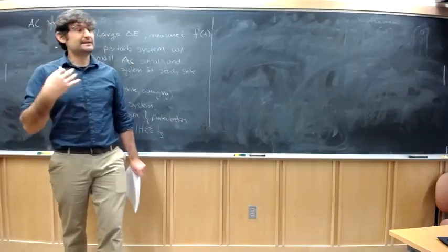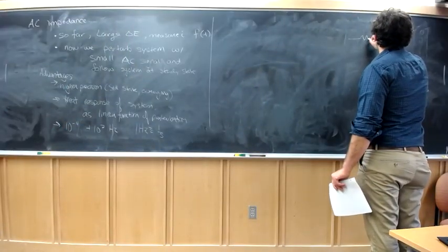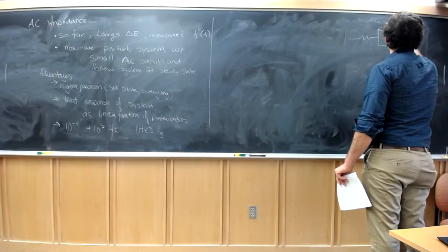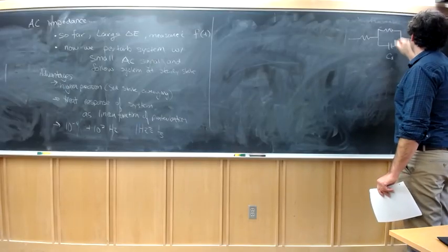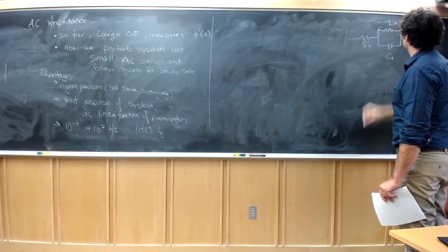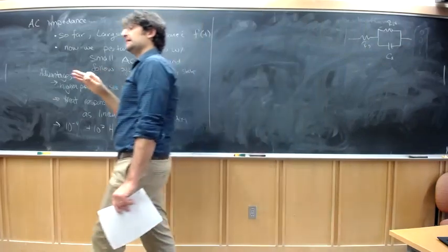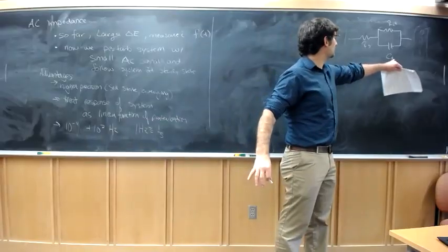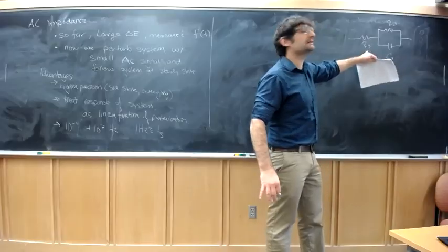The idea here is we want to build, for example, an equivalent circuit that represents our electrochemical cell, where we might have some capacitances and some resistances that represent different processes in our cell, and we want to use impedance to deconvolute the actual capacitances, for example, of the electrode, charge transfer resistances due to Faradaic processes, and series resistances.